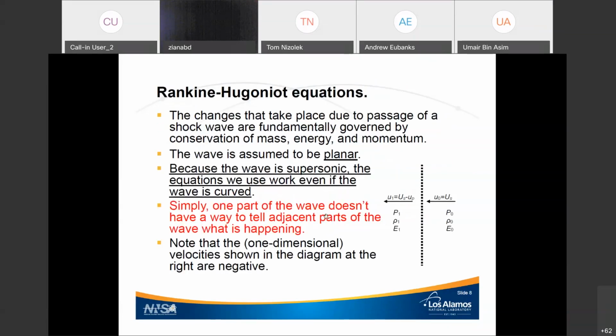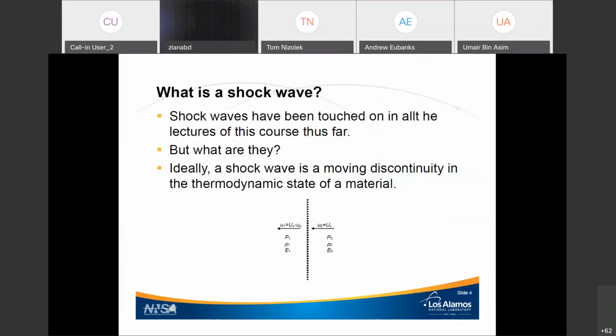Now, I discussed the fact that if you now sit on the shock wave, so as far as you're concerned, the shock wave is stationary and the material is flowing in and out. The material changes. Its thermodynamic state changes. Pressure, density, internal energy, velocity all change.